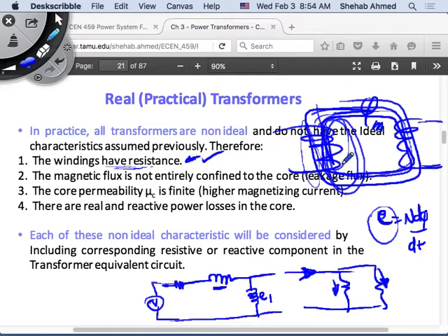So it's a drop in the path of producing my useful voltage, which is the one across the magnetic core, or the representation of the flux flowing in the magnetic core, which is E. That's why I put the leakage flux component in series here, and the resistive component in series here, because it's just burning power. I don't care. It's not doing this transformer action that I'm trying to create. So it's also a series component that I have here. And then now I can represent my transformer action.